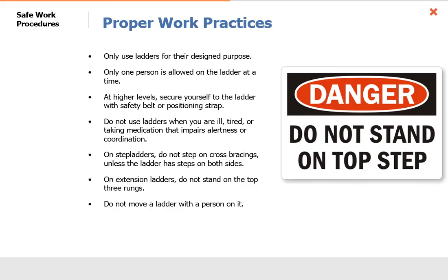Proper work practices. Only use a ladder for its design purpose. Only one person is allowed on the ladder at a time. At higher levels, secure yourself to the ladder with a safety belt or positioning strap. Do not use ladders when you are ill, tired, or taking medication that impairs your alertness or coordination. On stepladders, do not cross brace unless the other ladder has steps on both sides. On extension ladders, do not stand on the top 3 rungs and do not move a ladder with a person on it.